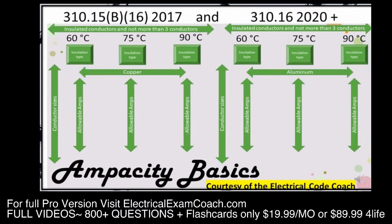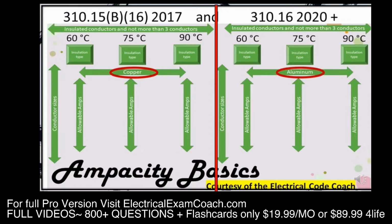The first distinction we want to make with this table is that it's actually two tables. On the left-hand side is going to be for copper conductors, and on the right-hand side is going to be for our aluminum and copper clad conductors. Left-hand side copper, right-hand side aluminum. And if you'll notice, they mirror each other, but in the NEC, it's smushed all into one table. Now let's take a look at what all this information means.